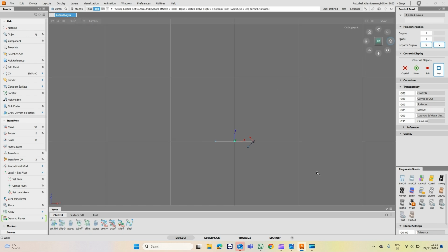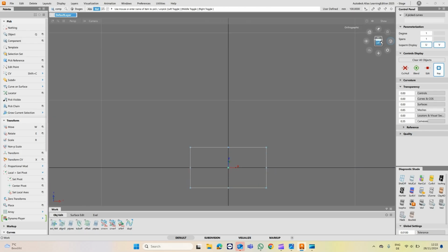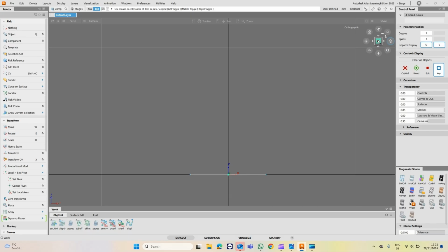I'm switched into the left view and I've got that. So I've got the perimeter there. And I'll copy paste this group and I'll move it in Z 90 millimeters. So 0 for X, 0 for Y, and then 90 going up.